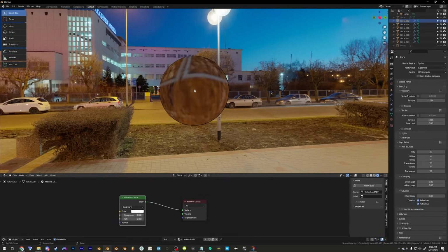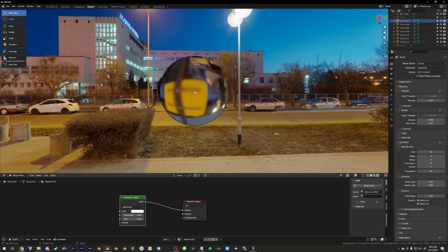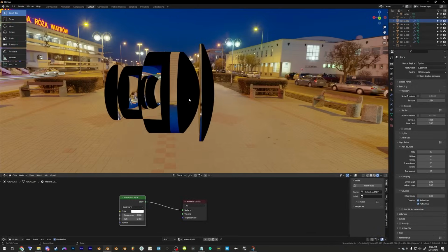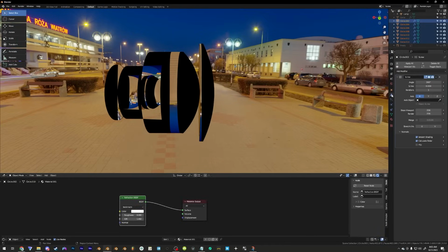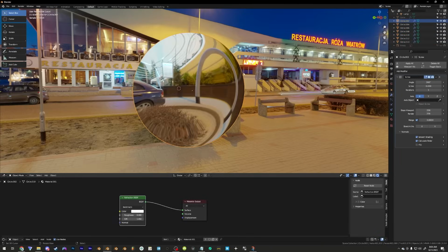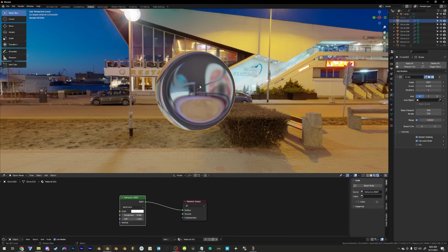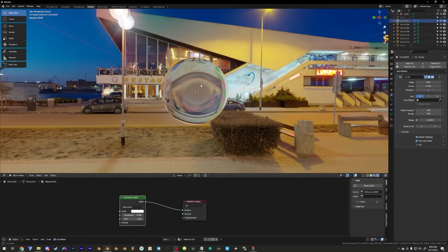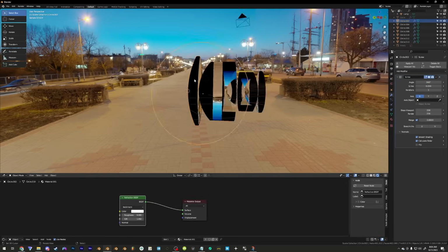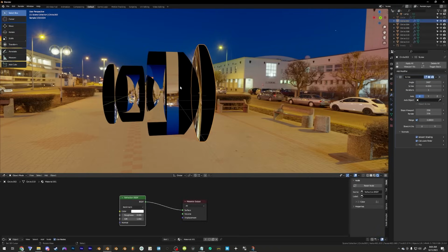However, we can still see that in the middle of it, there's this little pincushion, or this little pin right there. That will add a lot of distortion to the image in the future. That's actually a step that I missed. Hold Alt, that is how you apply everything to one of these, or from one to all of them. Hold Alt, click Merge. Hold Alt, edit this number, and set that to something unreasonably low. Now, if we isolate our lens again, we can see there is no more weird points in the middle of it. Perfect. Now, we're gonna go along these and see if the lens is doing what it needs to do.